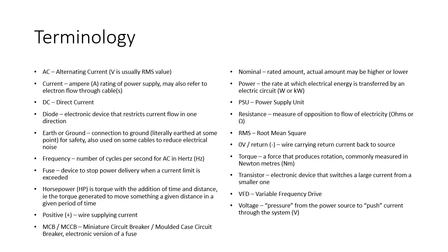But with most VFD applications, we normally assume they're balanced. If they're not balanced, you would use a reactor to improve the balance. But with most VFD applications, you just have the 3 wires and they're wired in a delta arrangement. Torque is a force that produces rotation, commonly measured in Newton meters, and there is a conversion we can use to calculate from torque to get to kilowatts and get to horsepower if we need it.